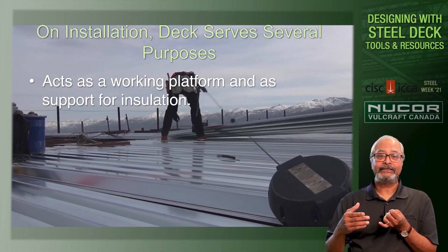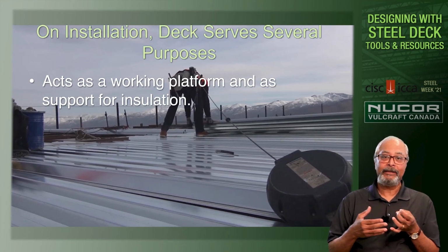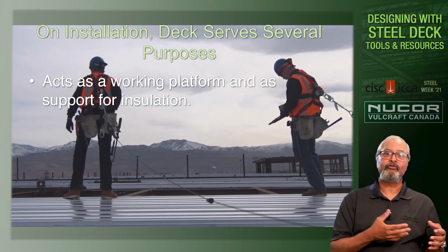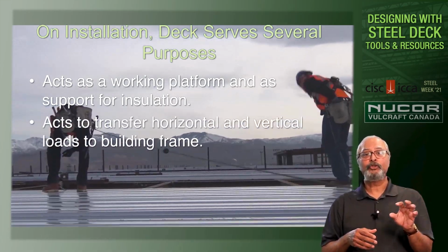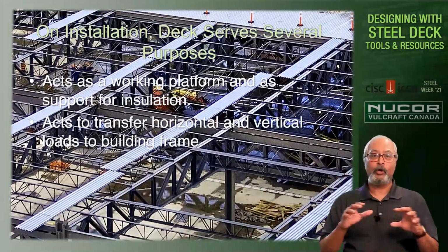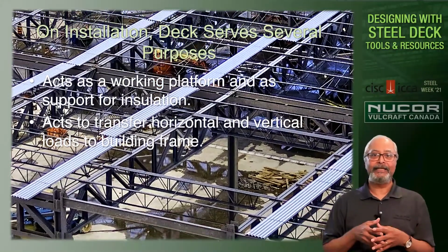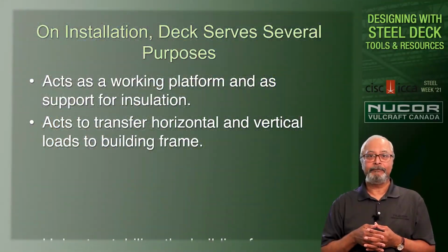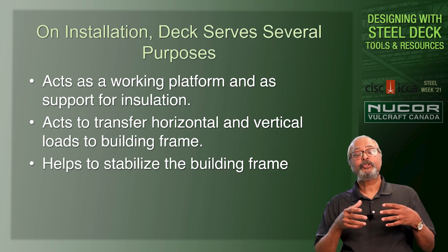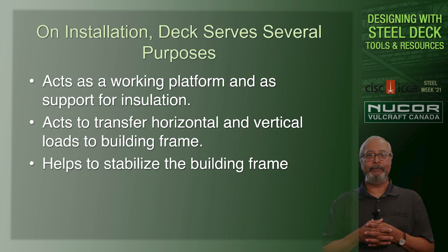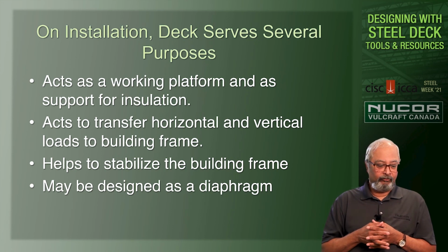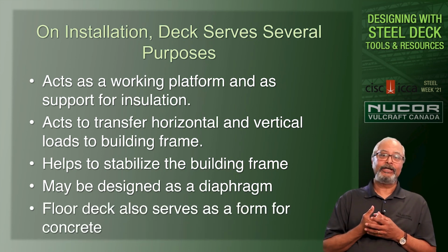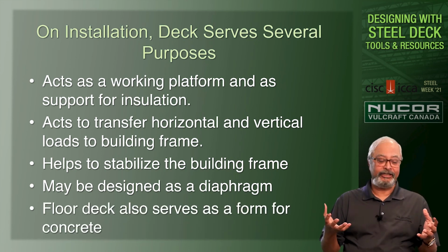One, it acts as a working platform and a support for the installation. Secondly, it acts to transfer vertical and horizontal forces to the building frame. The deck helps to stabilize the building frame and may be designed as a diaphragm. Floor deck also serves as a concrete form.